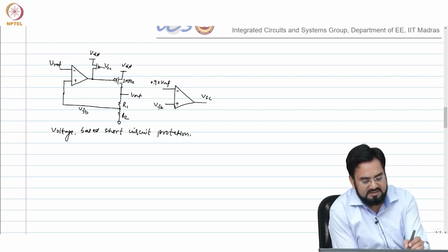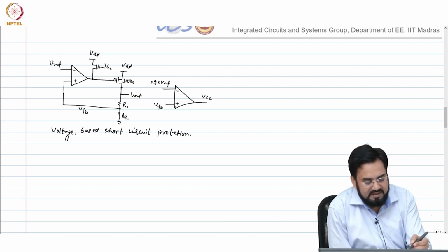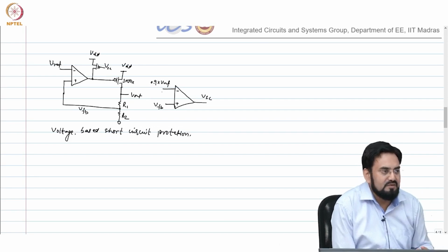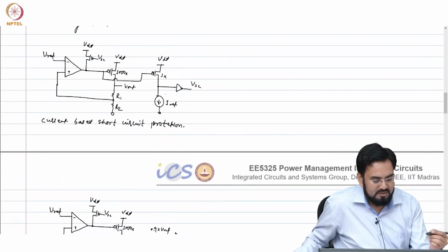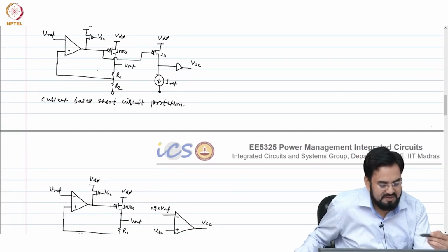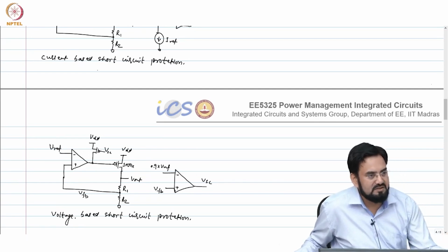So this threshold depends on you. If you think that when it goes to 0.9 it can still carry that much current, you can define it slightly lower, 0.8, 0.7, whatever you want. So sometimes we use both of them actually. Whichever occurs first, you just take the decision on that. Okay.